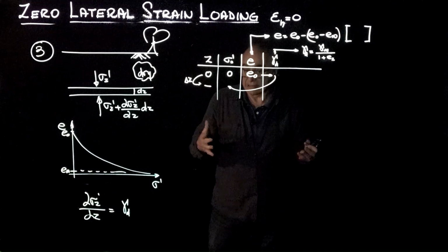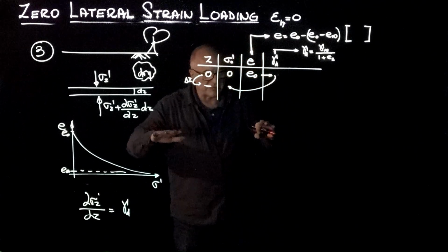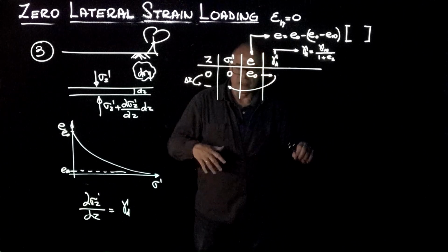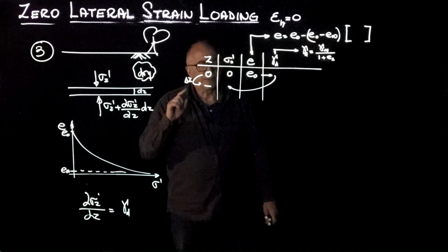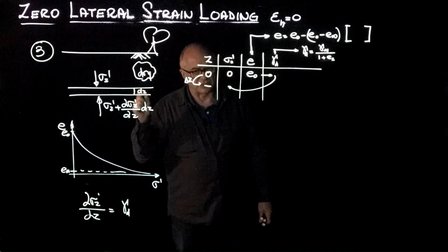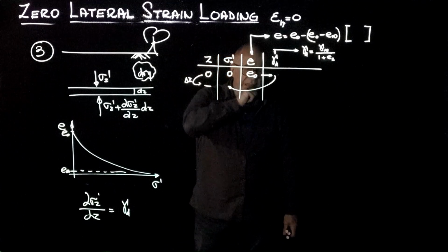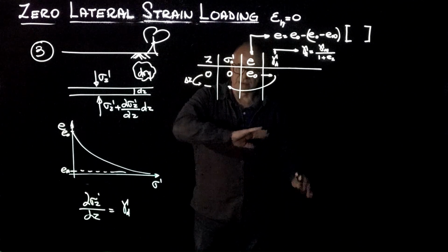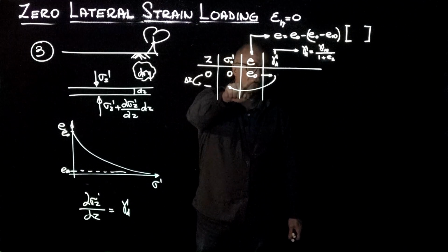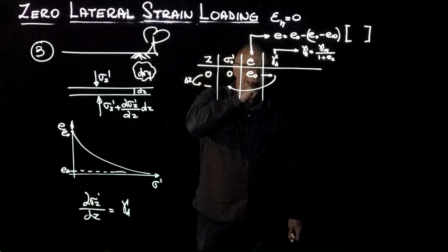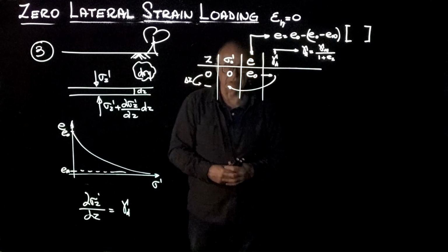Clearly, now we can anticipate the evolution, not only of effective stress, but also of void ratio with depth. It could be underneath the footing, but we can also do it for sedimentary basins. And you may remember from earlier presentations that the asymptotic void ratio was dependent on the soil-specific surface and other characteristics of the soil. So that's a parameter that you will need to know, or that you will measure, or you can extract from those charts.